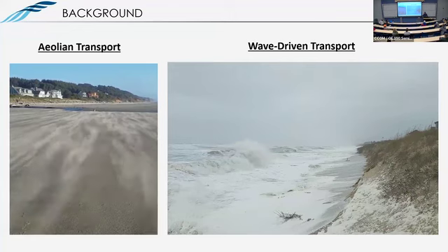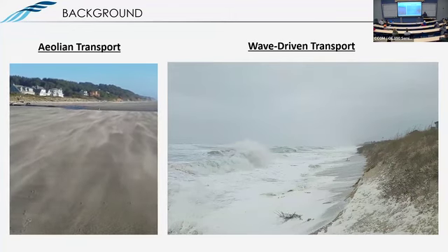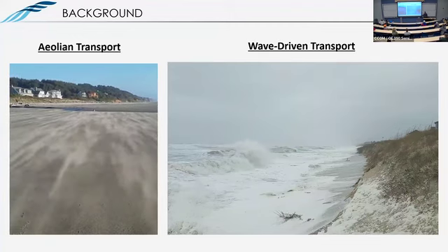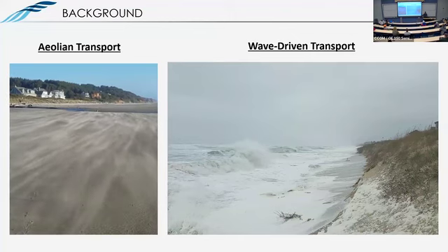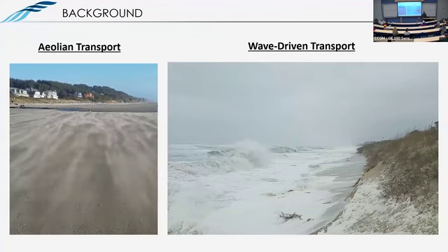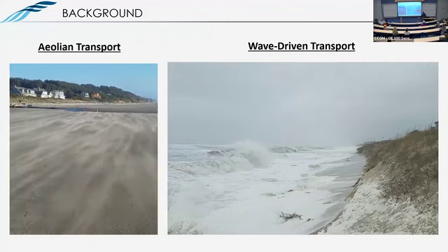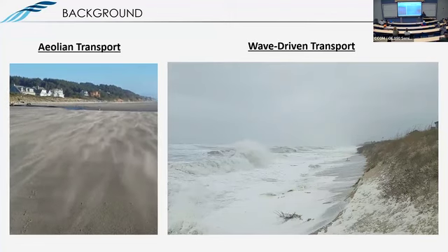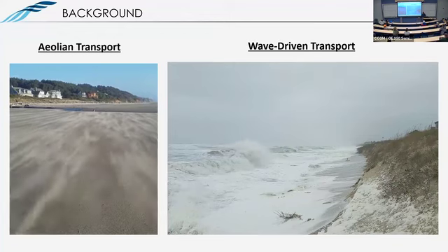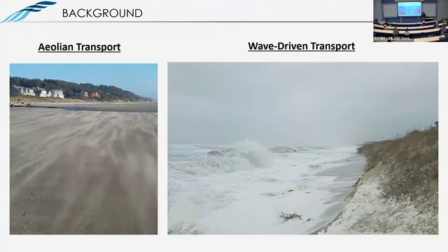I mentioned it before, but I didn't talk in detail about where I think some of the lidar technology could be useful: you are measuring that effect. We know when there's continuous transport across the whole beach, and we know when there's spatially intermittent transport. With that, I think we can inform what those two thresholds effectively are. The continuous transport is more analogous to how we currently treat wind-driven sediment transport in steady state models. But the reality is most of the time we're in this zone of quasi sediment transport, and that's where we get things really wrong.